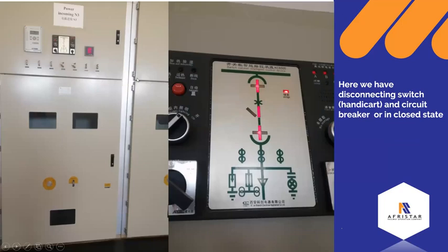So this is the hand cut switch, and we usually turn it on or off by inserting our tool here at this point and rotating such that the switch either moves to the front side or to the back. When it moves to the front side, we turn it off.